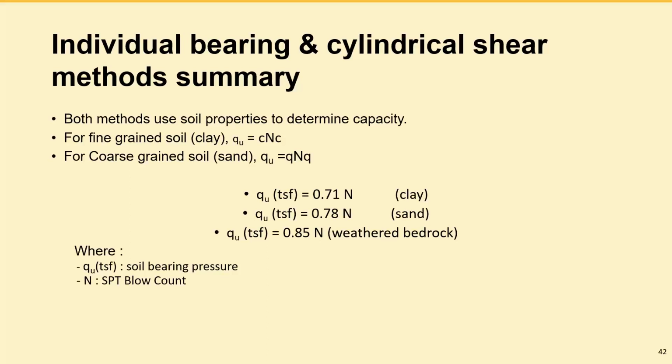We tested these helical piles and came up with the ultimate pile capacity, then went back and calculated the bearing capacity of the soil as a function of blow count N. So for clay, the bearing capacity of the soil in tons per square foot, this is not pounds, you have to multiply it by 2000, is equal to 0.71 N.